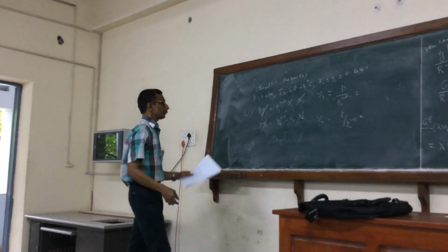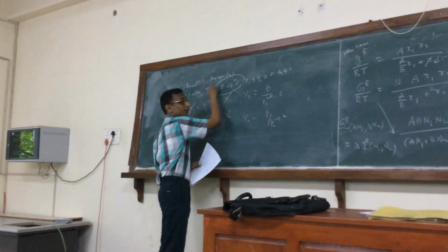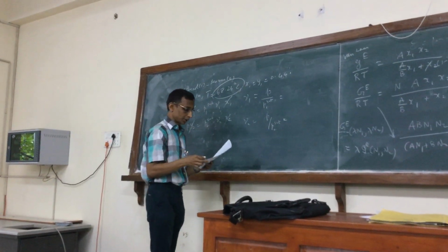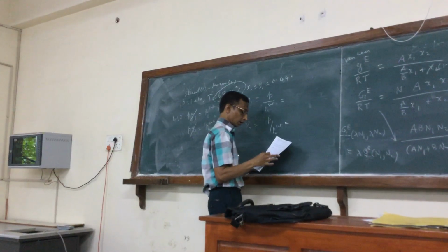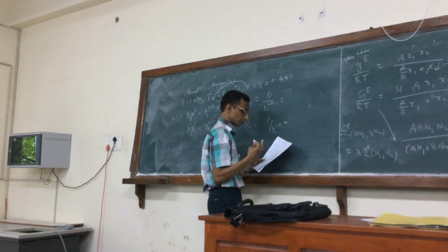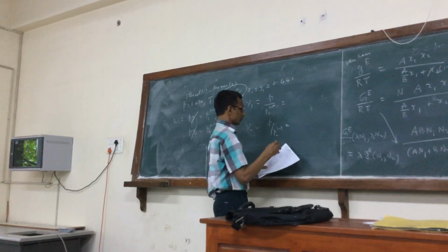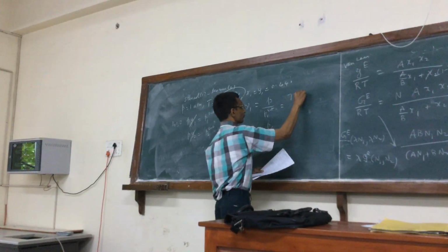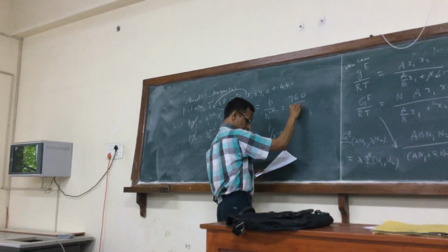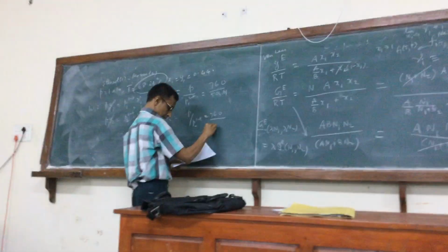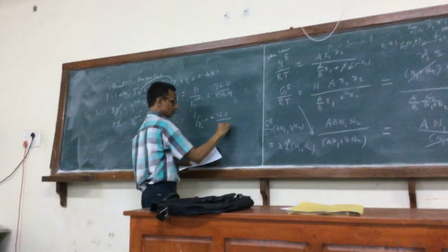So P1 sat must be evaluated at this temperature, that's the azeotropic temperature, because everything corresponds to a particular point. The gamma is also local, corresponding to a particular composition, namely the azeotropic composition. And then we saw P1 sat was 503.61, and P2 sat is 519.75.